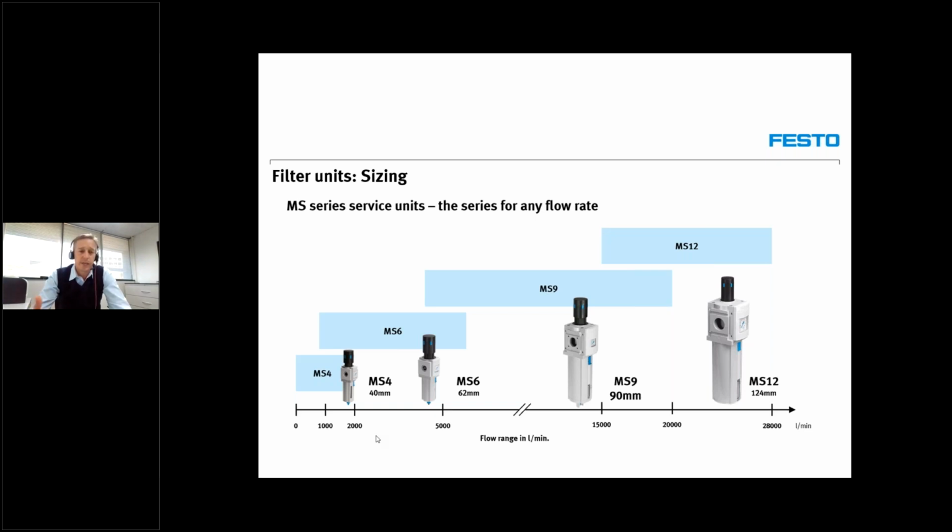What is happening is, you get a jerky movement, the pressure at the back of the piston reduces so much that it cannot overcome the friction. Then it slowly builds up, and when it overcomes the friction between the piston and your body, it jerks forward again, and that is why you've got your stick slip effect. So as soon as you've got a cushion at the back, and that cushion prevents that cylinder from jerking forward, then you get a much smoother movement of your cylinder.